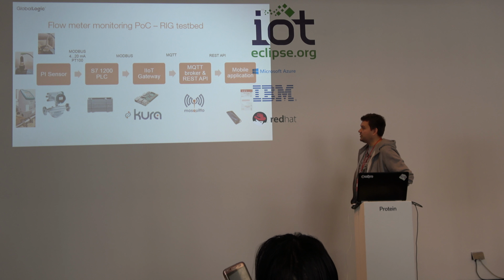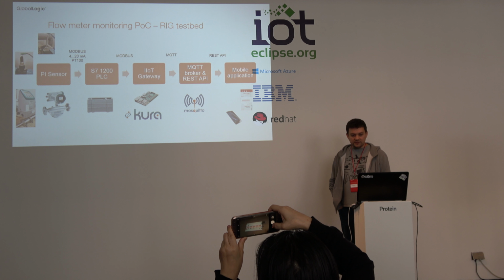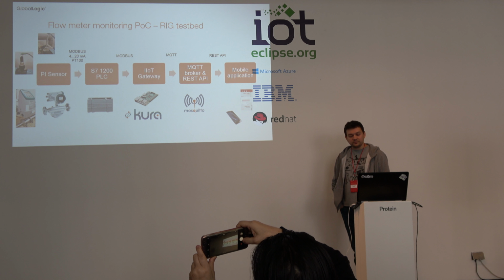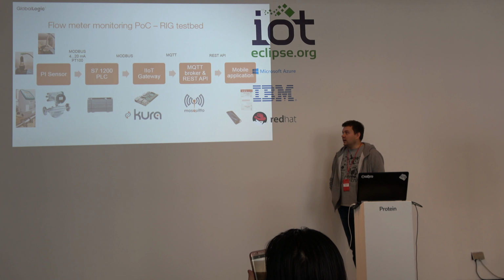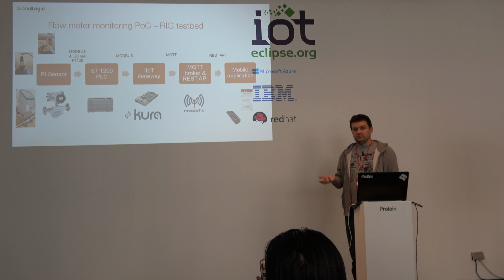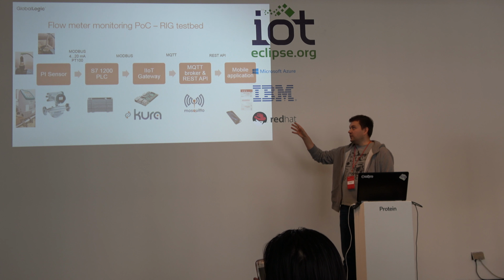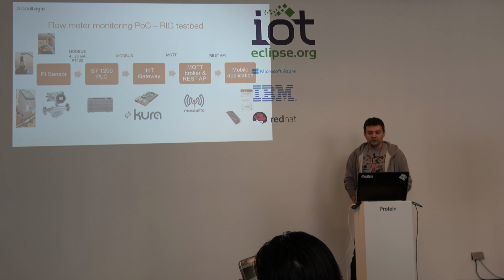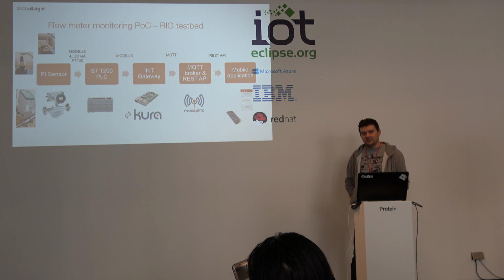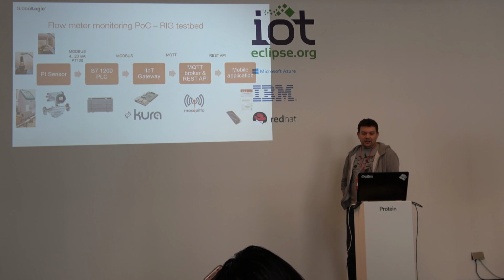This is the whole picture of our system, the flow. On the left-hand side, you can see the sensors, which are connected using different protocols to the PLC. The PLC is aggregating them, and those 2 blocks on the left-hand side are an abstraction of the real industrial installation. Of course, very simple in this case. And in the middle, the IoT gateway is connected using the Modbus protocol to the PLC, the most common, very old one, but really right now used everywhere.